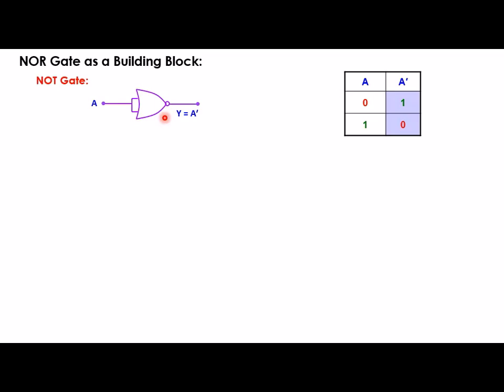And to that y you are applying a NOT gate. That's why you are finding out the output is complement of A. That's how this NOR gate is behaving as a NOT gate. To get a NOT gate from a NOR gate, you just have to join both the inputs together and give an input, and the truth table will be like this.